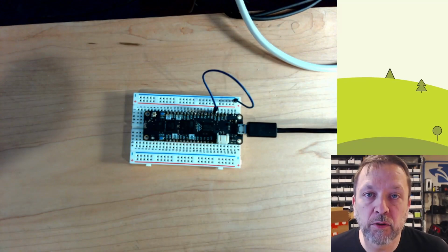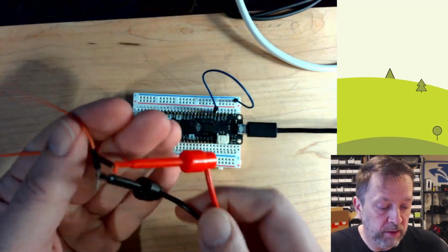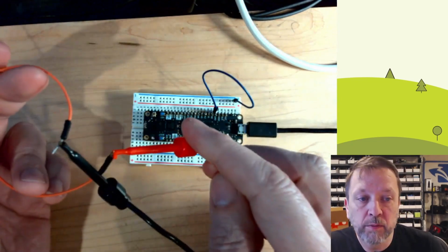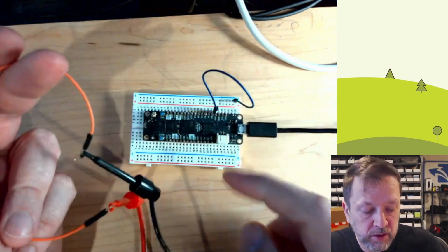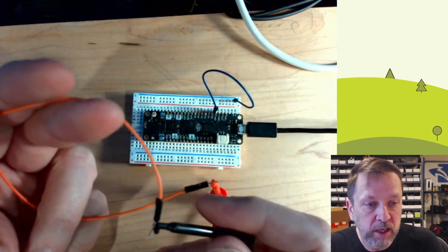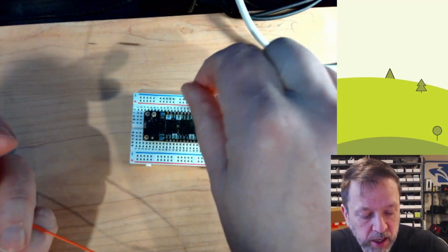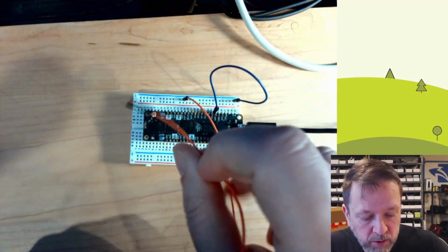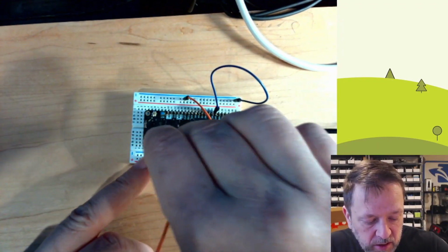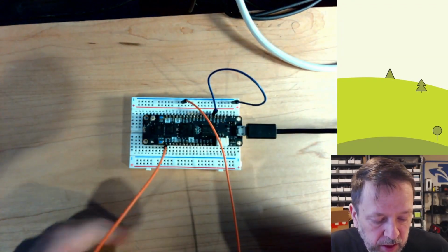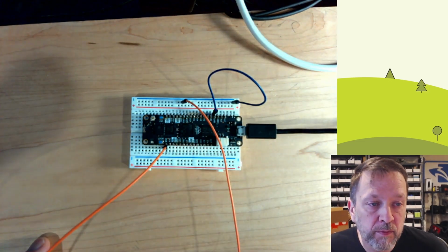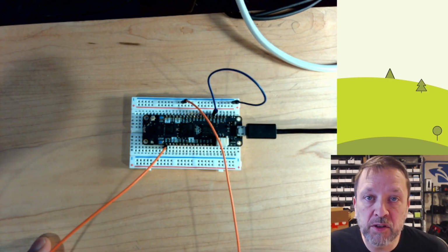So to hook up the hardware for this test, it's pretty simple. We've got leads that come from the signal generator, basically positive and negative. So this is generating the signal here, and this is the ground. We'll just connect the ground to the ground on the device, and we'll connect the signal to D05 here. No particular reason, it's just on the end, it's easy to find. Now let's go take a look at some code.